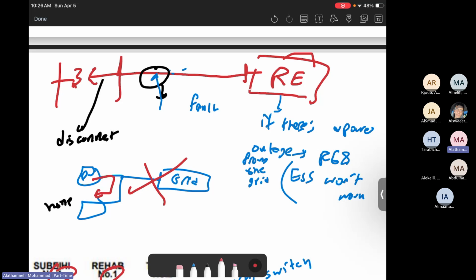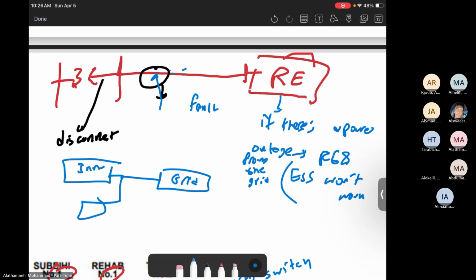Theoretically yes, but right now you are not allowed based on the configuration. Why are we not allowing it? Maybe the power has been disconnected because of the transmission, or because of faults, or because of maintenance. So we don't want you to shock the crew. So here is an inverter, and here's the photovoltaics. The inverter is programmed to detect the grid voltage.